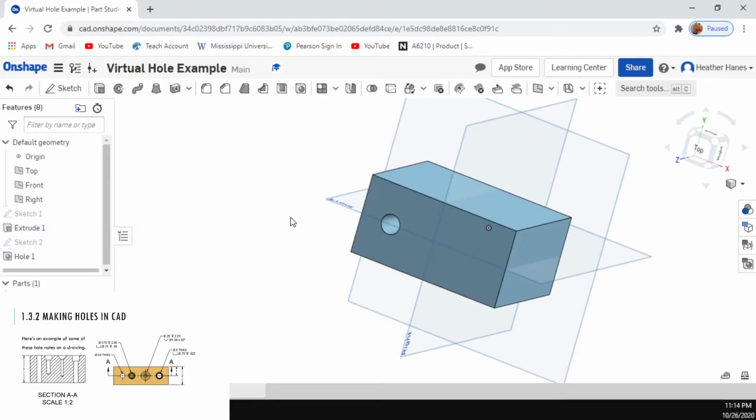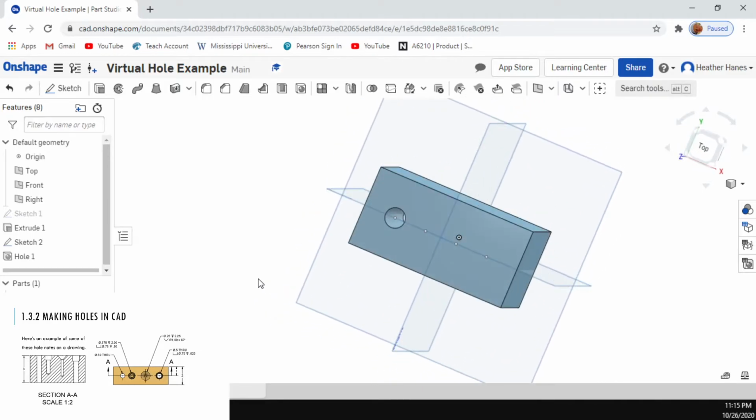And normally it would automatically then hide that sketch so you don't see those other dots. So I'm going to just remind you, you can always show things. Like I noticed a lot of y'all when you did the first part of the 9 weeks test on OnShape, there were those 2 wings that came up on either end of the thing that looked like a couch or a footstool or something. A lot of people drew both of the rectangles they wanted to extrude, and then they only extruded one, and then when they got out of that extrude, it had hidden the rest of their sketch, and so they had to redraw that rectangle. So they had extra features over in the feature list. And I just noticed that was a common thread.